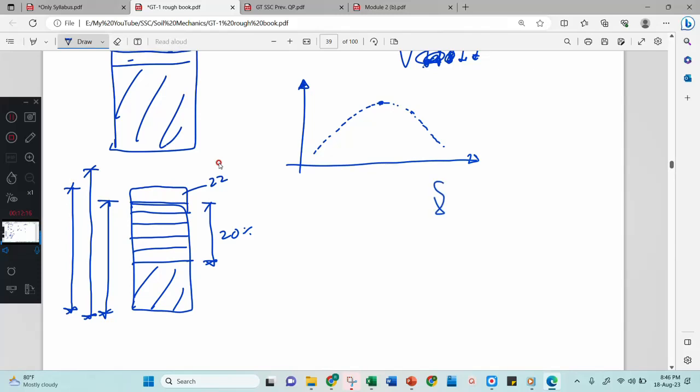Now in the second phase, mass and volume are increasing because water is added beyond saturation, and mass is increasing because water is added. Both are increasing. Then what decision do we have to take here? But the density is decreasing. Why is density decreasing? Because the volume increment compared to the mass increment will be more, with two arrows, therefore the density will decrease.